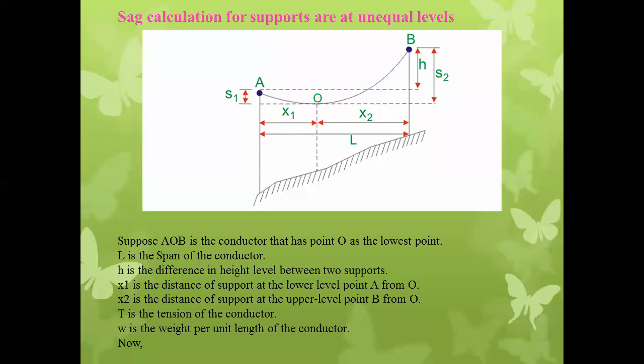In that case also we have to calculate the sag, and indirectly we can decide the span also. While calculating the span, generally it is calculated by a civil engineer. I think an indirect surveying method is used to calculate the span between unequal level supports. Generally the span is decided by civil engineers, and the span of unequal levels is calculated by the indirect surveying method. Remember there are two types, direct and indirect surveying. In indirect surveying, when we stand at one point the other point is not easily visible, and they calculate it using their instruments. How to measure that span is not our part.